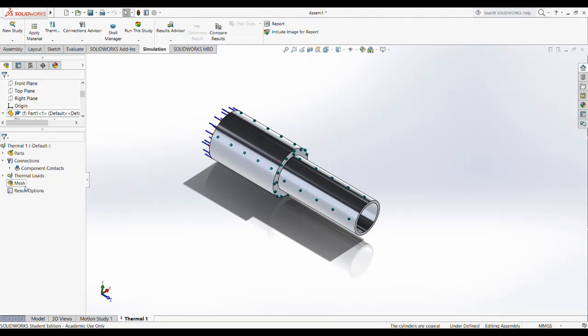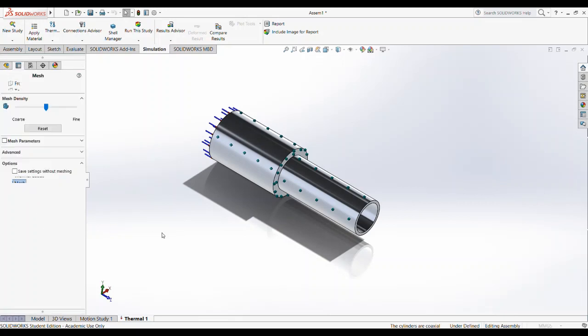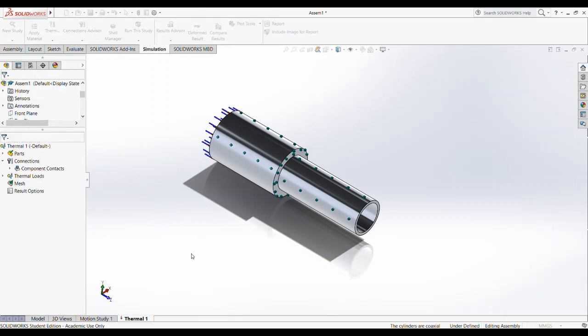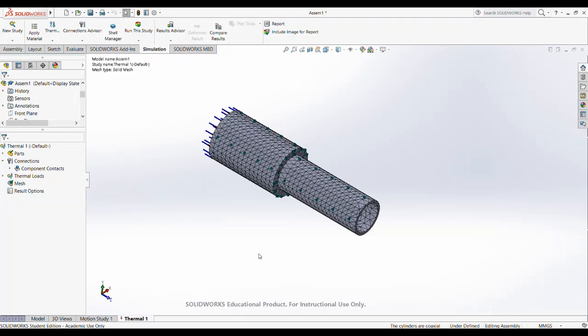Now I need a mesh. Create the mesh. Remember, this is actually a finite element solver. In chapter 5 we talked about finite differences. This is not a finite difference program, but it's on a similar concept. Finite element. You right click mesh and just say create mesh. That's going to give you a default setting, and just go with it. Say OK, and that's fine. You just go ahead and hit the default here.